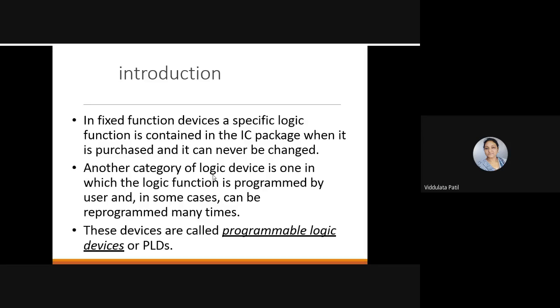Once you purchase that IC, you cannot change the function of that circuitry. It will work as a NAND gate only. But another category, the logic device, is one in which the logic function is programmed by the user. Once you purchase that, you can program whatever logic function you require. In some cases, once you program it, it may remain as it is, depending on your application, or you can reprogram it many times in some cases. These types of devices are called programmable logic devices or PLDs.